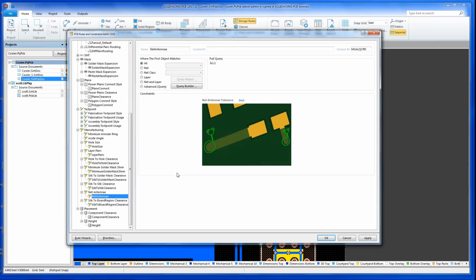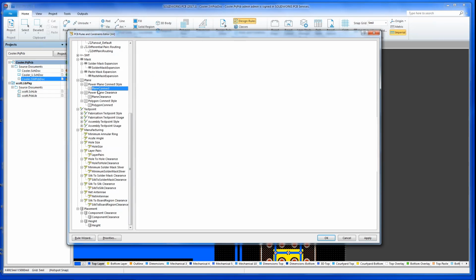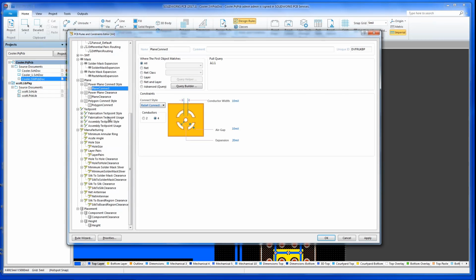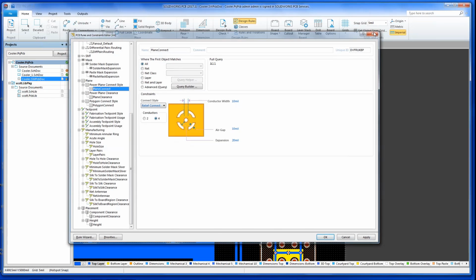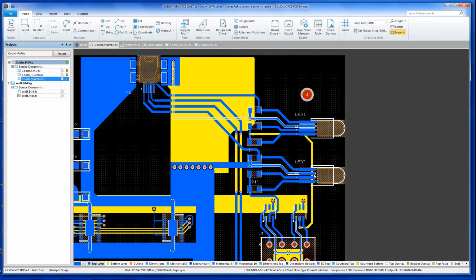Make sure you don't get stubs out there radiating energy into other circuits. Connectivity, power plane connectivity. You can do direct connects. We can do thermal ties. The tool is extremely powerful and can produce most all of today's current technologies, including HDI, high-density interconnect with microvias, sequential lamination boards, not a problem, control impedance boards, no problem, differential pairs, high-speed boards.